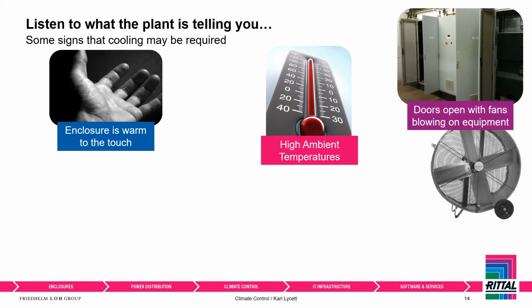Next one. A lot of people do this, but if you have your doors open to try and mitigate some of that heat, because you keep getting your drives clicking out on overheating, or you've got fans blowing on your equipment because nothing else is fixing it, I'm secretly judging you. All you're doing there is allowing dirt and debris to fly inside your enclosure. It's going to be attacking all your wiring, getting in your connections, and reducing the performance and the lifespan of your equipment. So it will not pay in the long run.